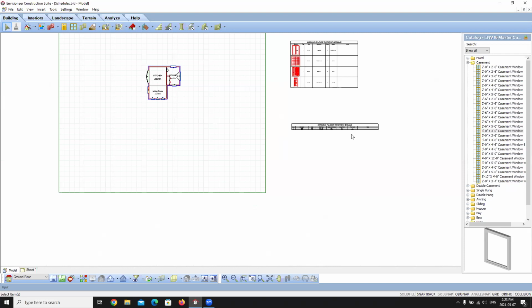So that's why by default, you're not going to have any framing assigned to basic floors. All that will be done under your structural floor. What we're going to do is we are going to convert in our drawing one of our elements to be framing.